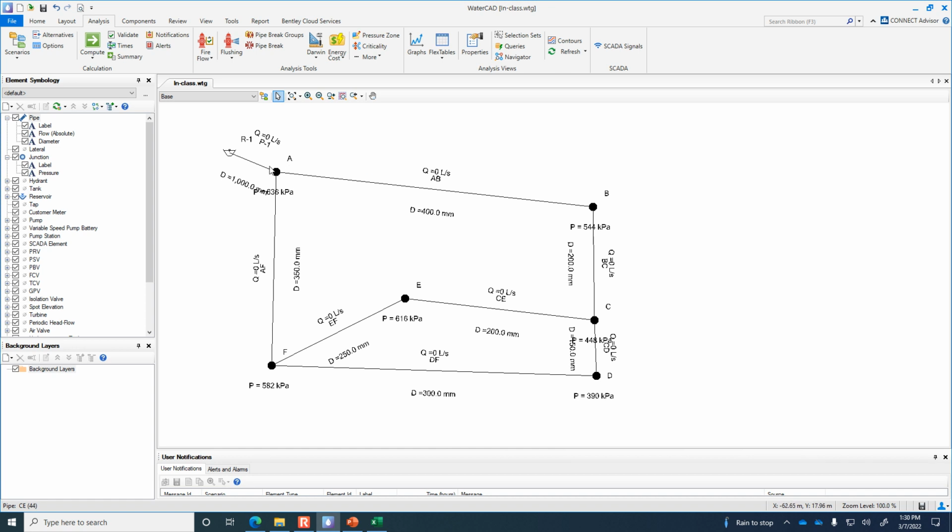So if I had the option, I'd move the reservoir higher up the hill, because the more pressure you've got under the static condition, that's going to give you more headroom to work with as you're reducing the pipe diameter. And this is a super important point. It seems like half the students in the class don't fully appreciate this relationship, that you want to have the reservoir as high on the hill as you can get away with, because that's like your currency for optimization. That's where your pressure comes from. And the more pressure you've got under the static condition means you're going to have more pressure under the demand condition, and you can make the pipe smaller and smaller and smaller.